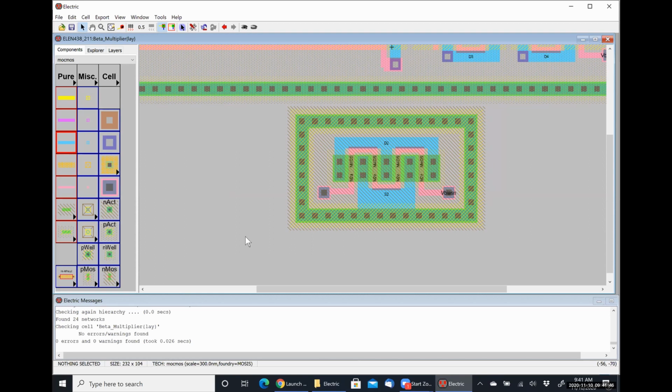So I just put a big chunk of P-well effectively covering underneath this entire transistor. But the reason why it doesn't give us an error is this gray thing with no lines over it is also P-well in this particular process.